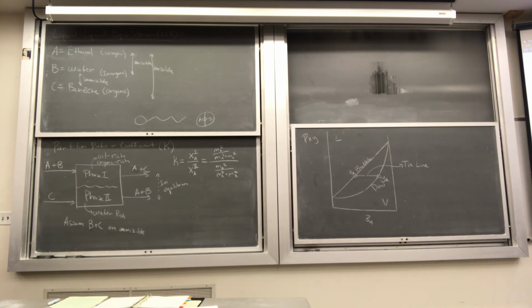So for example, here, see how that kind of pinches together here and it kind of expands out there? So this point 2, I would say is maybe, if I'm looking this way here, maybe like 60% from the top line and maybe 40% from the bottom line. Does that seem about right to you guys? So that means my tie line would need to connect the points that are about 60% down from here and about 60% down from here, right? So I want to think of this like a fan opening up, not just shifting this one parallel and shifting this one parallel. Okay? So that is how we read the triangle diagrams.